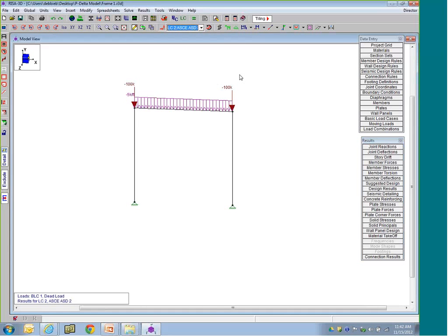Okay, load combination 2, what is load combination 2? It is just some dead load and live load. It's really not a lot. There's actually no wind load in this case. And what we can do is look at our deflection. So the deflection sort of tells the story for us here. It tells us that, wow, this whole thing is sort of buckling, just under its dead and live loads. So we can really see that there's probably not enough stability in this model to work with that.